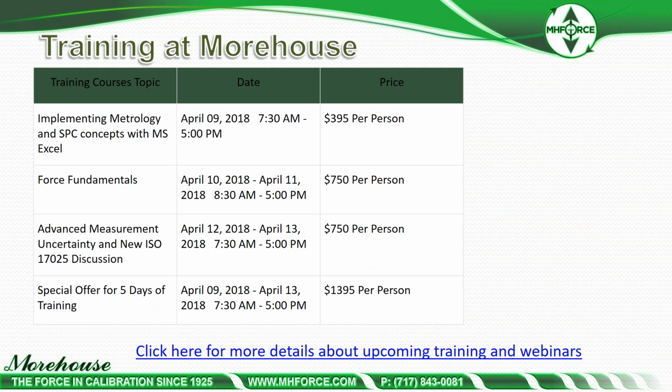Our next webinar is not scheduled yet. It's tentatively going to be titled ISO 376 Explained. That is a force standard. Most of Europe is using that force standard. The only thing I have to say right now about ISO 376 is it is not the same as ASTM E74. So if you're working to E4, you need ASTM E74 as a standard. If you're working to ISO 7500, you need to use ISO 376 as the calibration standard.